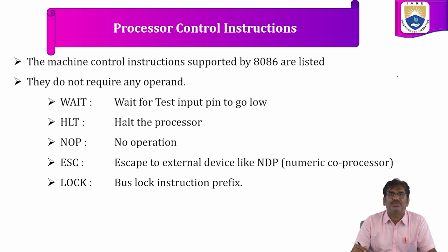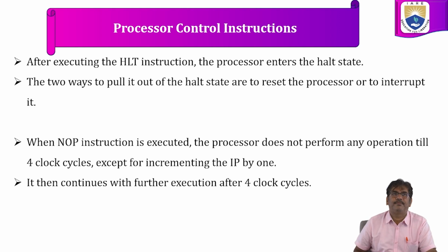WAIT is to wait until the TEST pin goes low. HLT halts the processor. NOP is no operation. ESC is escape to an external device like the NDP, numerical data processor, which is a coprocessor. LOCK is a prefix to any other instruction, which locks the bus. Now we will see the detailed explanation for each and every instruction.